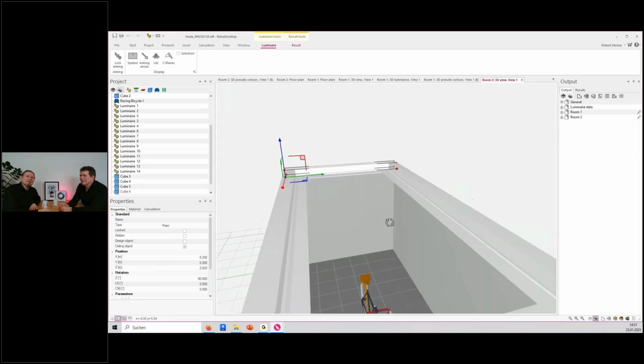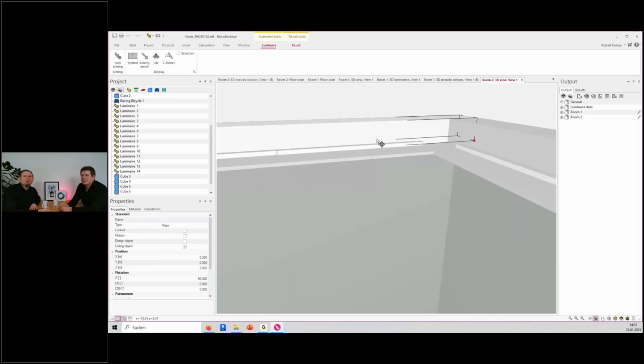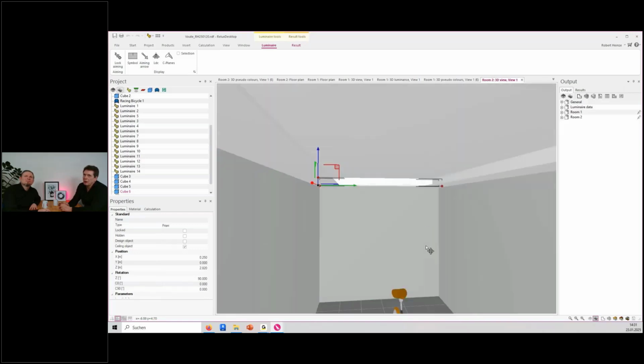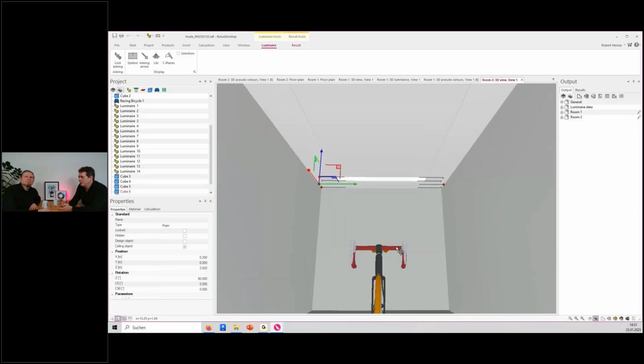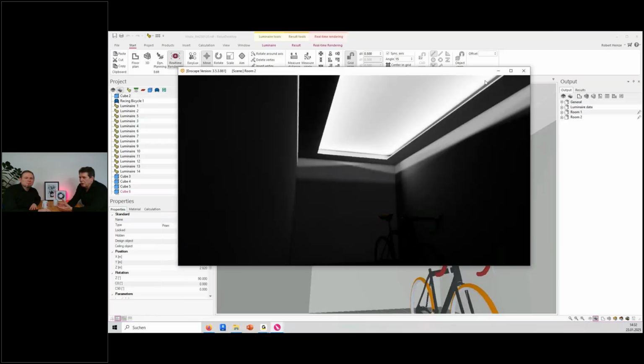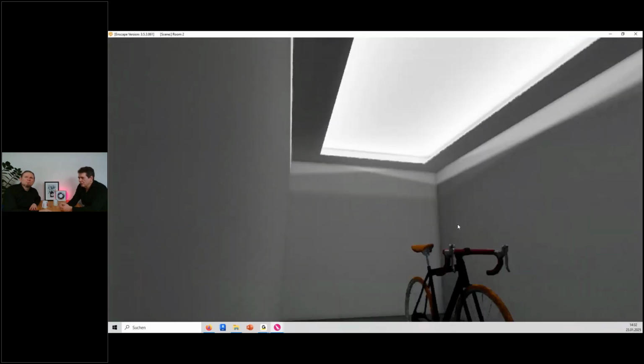It's also hard because you depend a lot on the material information, so you have to be really sure what this reflection you have here on this surfaces. Because in this situation, parts of the wall and parts of this construction cubes of the wood become a part of, let's say, a part of the luminaire. It goes in the function of a reflector, and if you have to have realistic results or realistic visualizations for things, you have to measure the complete luminaire with the reflectors in the gonio-photometric.